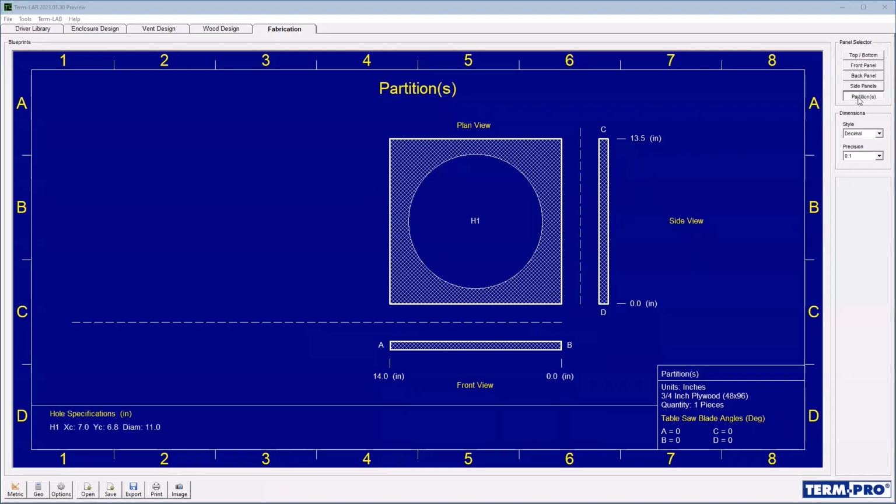The only difference is the partition has a hole in it. So, if you wanted, you could cut 3 of these. They're identical dimensions. A lot of thinking goes into the way these boxes are constructed. So you have minimum fence movement and you cut these panels all the same. When you put the box together, everything's going to fit. Otherwise, if one of these is off even 1/8 of an inch, you got a gap somewhere. And then you have to fill it in.